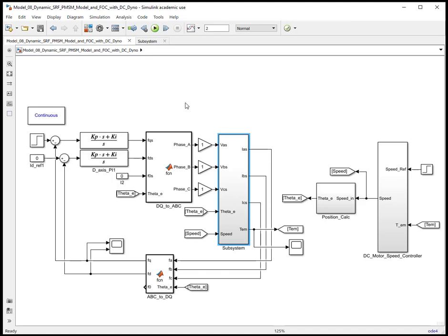So there was a request in the channel asking, how do we implement the inertia aspect and get some realistic simulation developed? This video is trying to provide that information. We are using the same model as before. The difference here is, instead of assuming that your speed is regulated, we have our torque signal fed to another Simulink model which contains the mechanical dynamics and the DC motor.